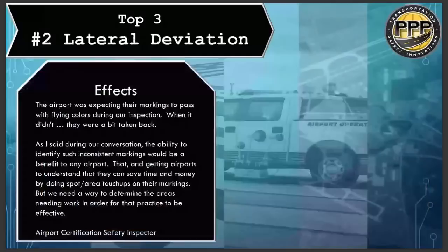Yeah, thanks, Greg. That's a good point. Anecdotally, I've seen markings, particularly on asphalt, that you can't even see them in the daytime. They're totally obscured by rubber, and you go out at night, and it looks like they were just repainted because you can see all of the reflectivity. You're not relying on that coating. You're relying on all the glass beads. So rubber's certainly a bigger problem for some of the top airports, the large hub airports, but a problem in many others as well.